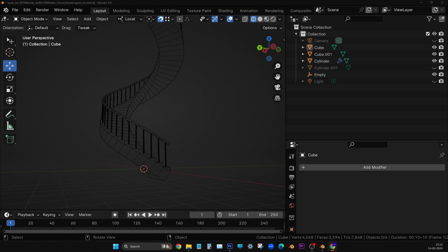Now you remember, I think we have to switch on the vertex snap. So where the snaps and all, no, not that one. Whenever we talk about snap, it is related to the horseshoe icon. Wherever the horseshoe icon, there all the snaps are there. If you see in the top, yeah. Near that one menu is there. Just open that. In that, vertex should be on. Yeah, that's all. Very good.